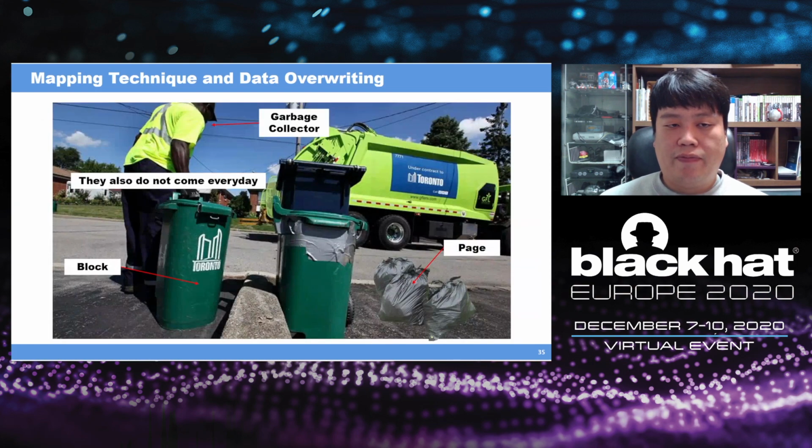It is a default feature of SSDs using the block level mapping algorithm that when overwriting occurs, the original page is marked as stale, and there is no choice but to leave it as it is, because erasing cannot be processed per page; it is done by block size. Therefore, the GC function generally erases all the pages together at once.